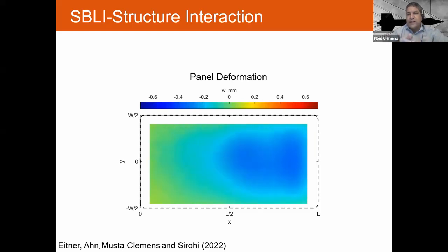And that's actually why we picked it, because from the shock foot pressure data, you see where the peak frequency is, where the most energy is. And we literally picked the thickness of the panel to coincide with that. So we're creating a situation where the shock foot motion is driving this thing very energetically, and it's driving the first mode.